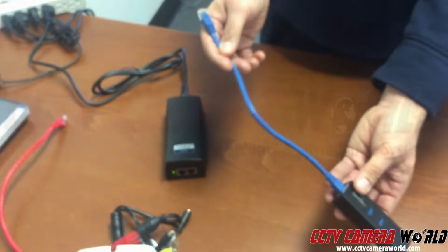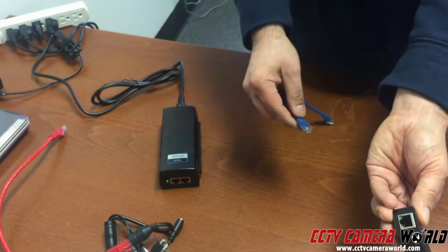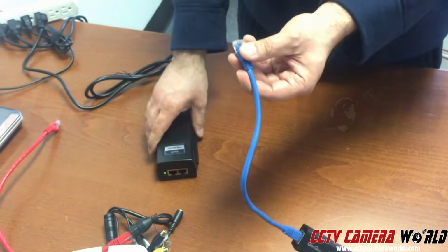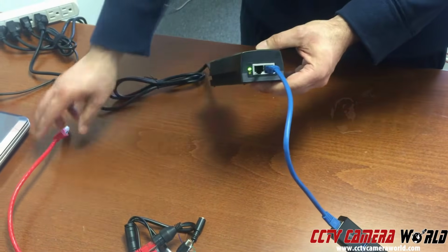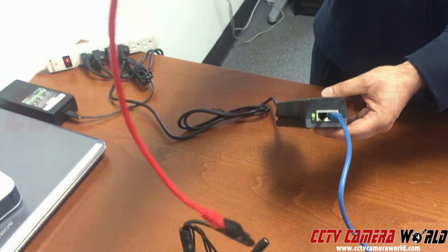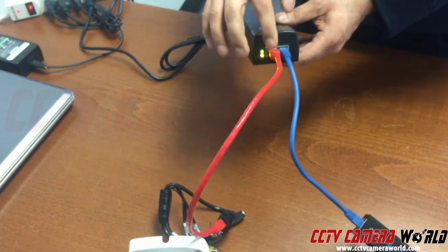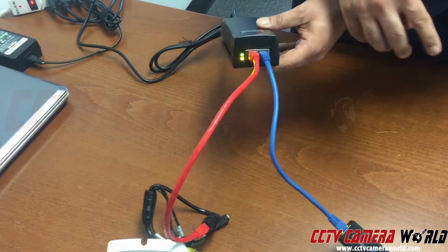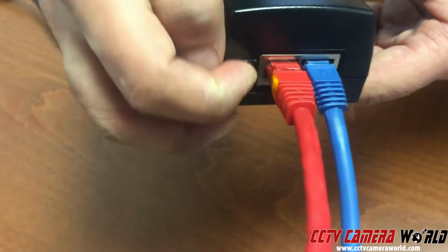Here, I've got a dongle connected to my Windows laptop. Because it doesn't have a built-in network port, I had to use a dongle to attach a network port. So I've got a network port here. I'm going to connect one cable, which in this case, the blue means data only, that I'm trying to illustrate here, and connect it to the data out into my PoE injector. And in this case, red for PoE coming from my camera connected to my injector. So now I've got power and data going to my camera, and this thing connected directly to my laptop using a different cable. And the PoE injector itself will light up and show you these lights.